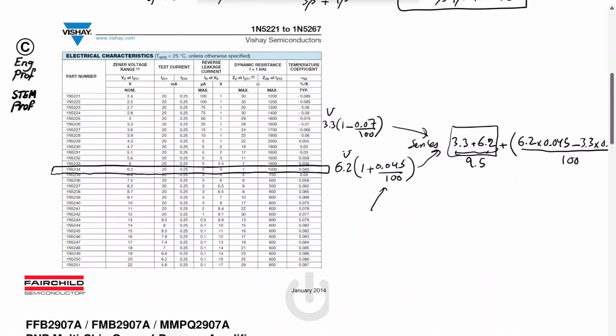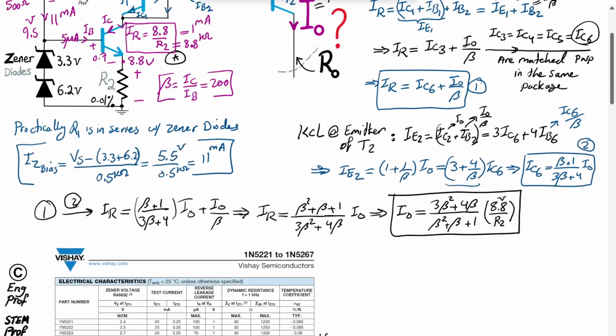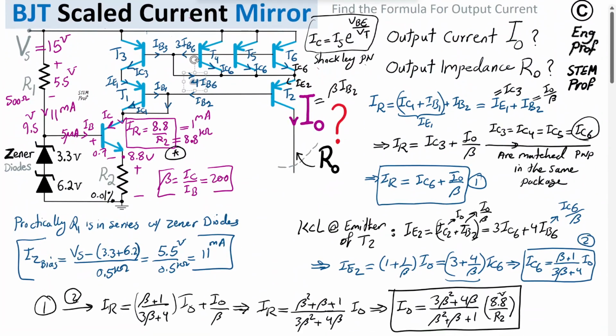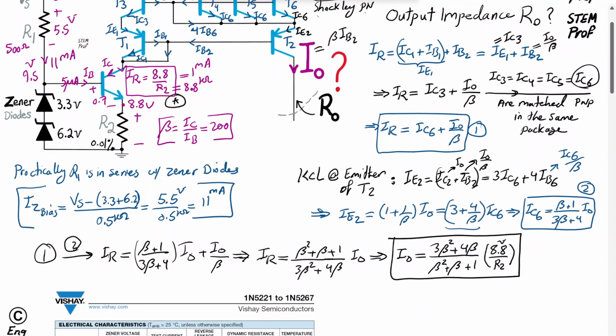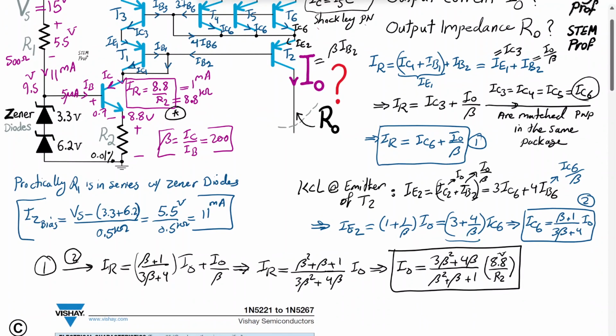So we want it to be as close as possible to what we believe is the base-emitter temperature variation of this transistor with respect to temperature. For example, we know that the base-emitter voltage of an NPN transistor drops by about 2 to 2.5 millivolt, depending on the type of transistor, per degree Kelvin or C.